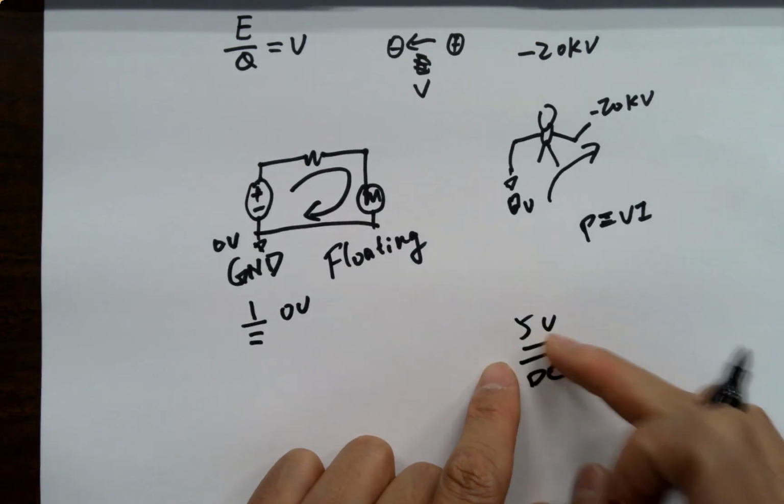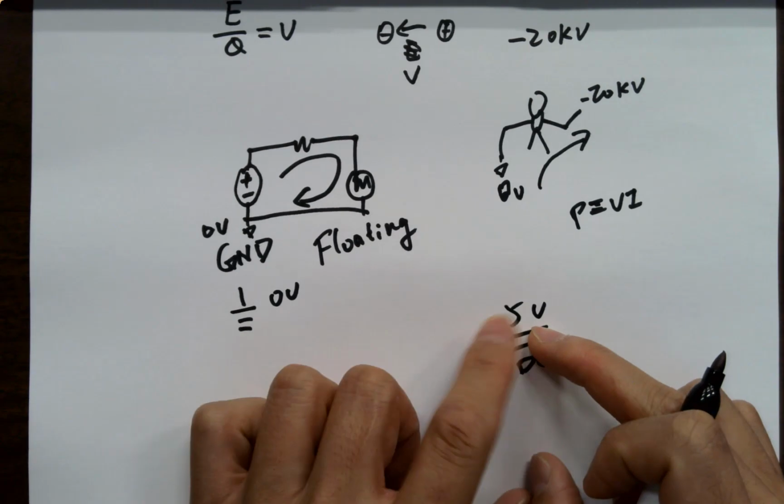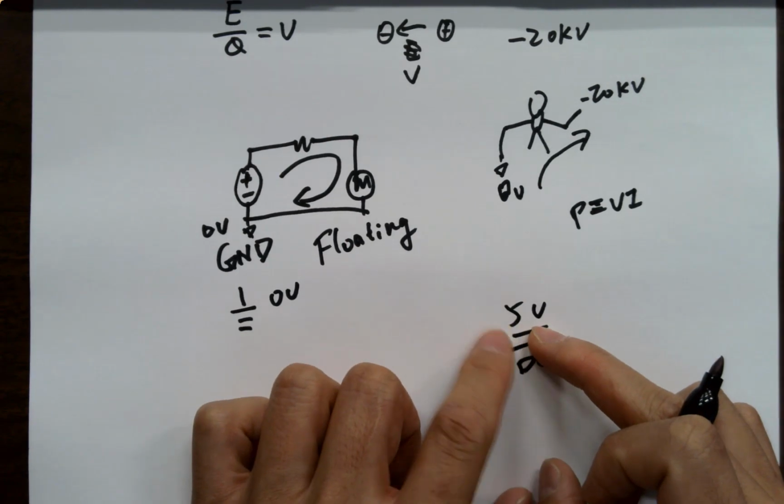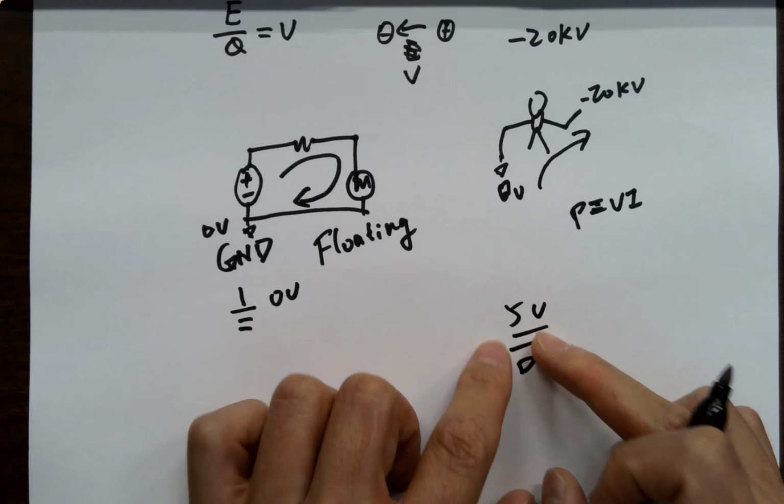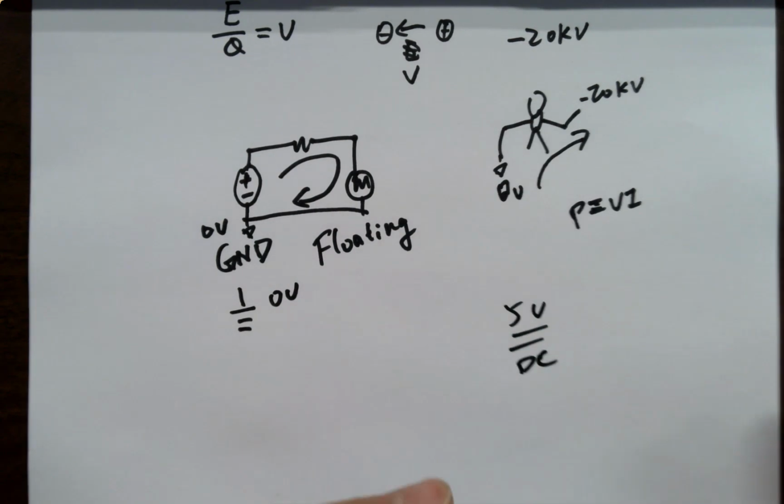And your 5 volts is usually from where? Anybody know that? Yeah, power, usually USB, right? USB is 5 volts, always. And some of the components, for example microcontrollers, not Arduino, but the ESP32s or other devices, only take 3.3 volts. 5 volts is going to blow it up.